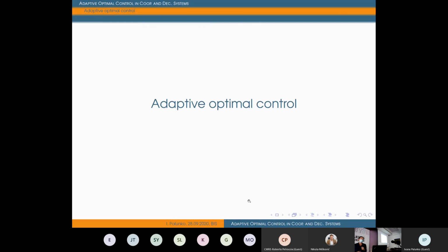So that's why we approached the notion of adaptive optimal control. Because if you have a standard model of the system, you can approach it, either linear or non-linear, from an optimal control perspective. If it's linear, then you use some kind of LQR, which is stable and optimal, which is perfect. If it's a non-linear system, then you somehow find a way to either linearize it or to find a solver that will solve your somewhat piecewise linear, non-linear system. If everything is perfect and your dynamics don't change, then your performance is very good, as desirable.